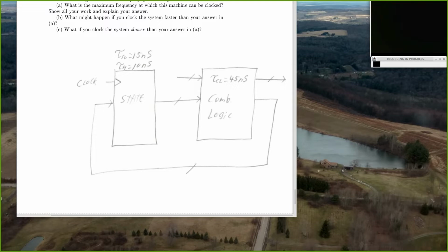So we won't necessarily be writing equations in the same sense that we did in the other labs. We won't necessarily be writing sum of products, which means we may not be using K-maps. But the way that we analyzed this and came up with a design for it, we ended up with 3 columns, yellow, green, red for each lane, and each of those was an output from a 2-input truth table, old green and delayed old green.